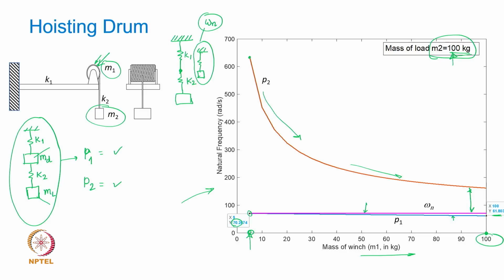so what is the takeaway from this? I mean, what we are inferring is that if there is a large gap or a large difference in the two mass values, at least the lower of the two natural frequencies has absolutely no difference when you compare that value of the first natural frequency with the frequency that you obtain by assuming a single degree of freedom model.